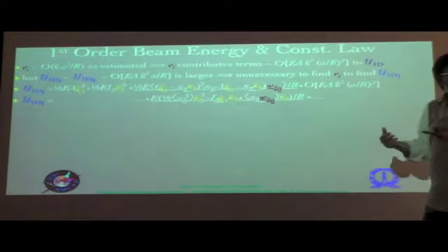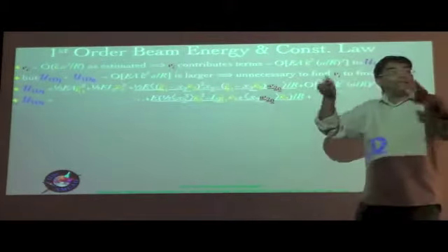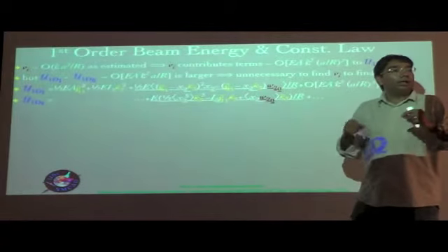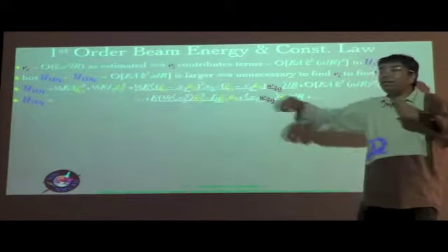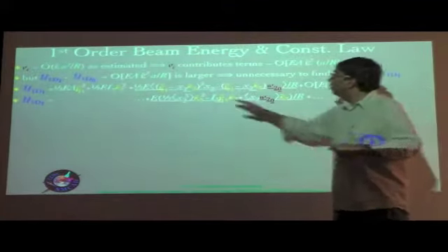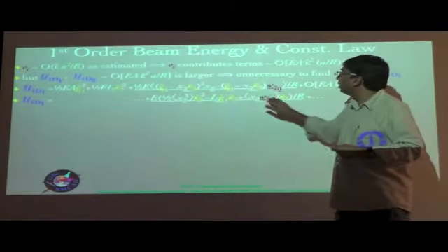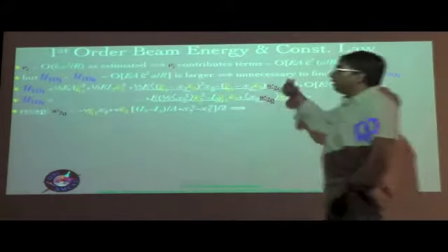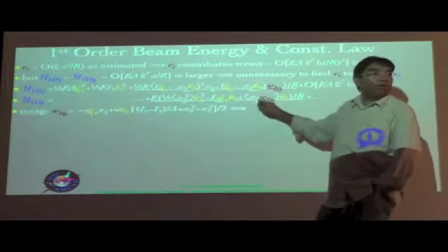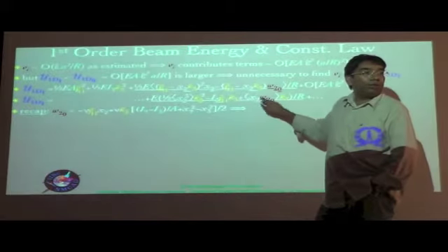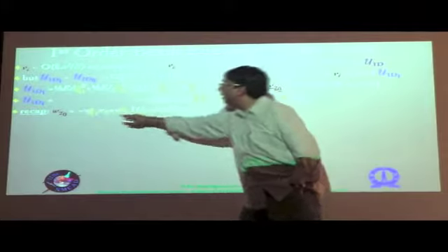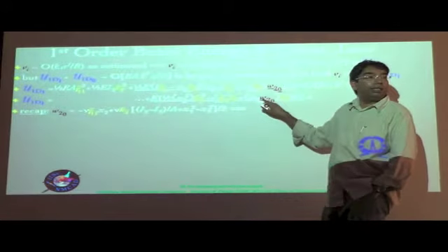Some terms will go to 0 as well, because of the fact that we have chosen the centroidal axis as the loci of area centroids as the reference curve, etc. Because of some of those reasons, some of the terms will vanish, and basically this is what you will end up with. Now we go back, because this is in terms of one of the zeroth order warping components, and that we have already solved for in the previous approximation. So we take that expression and we can substitute that here to further simplify this.